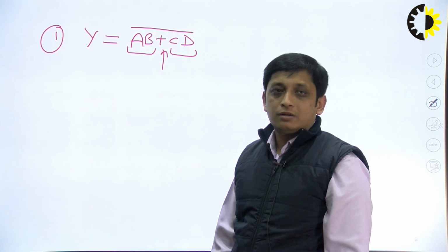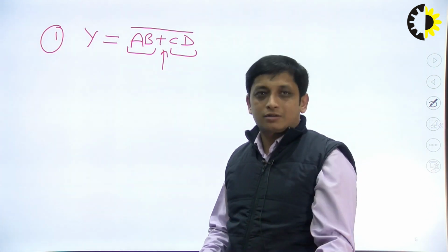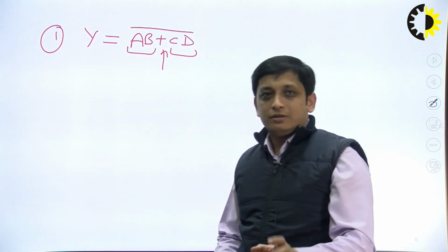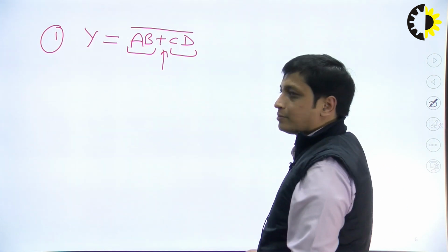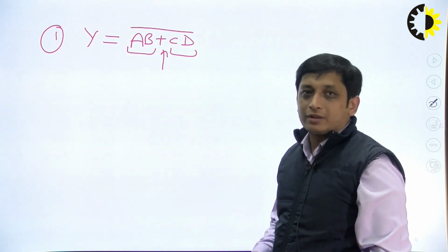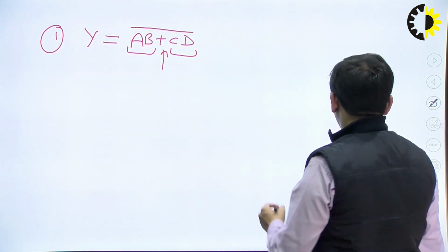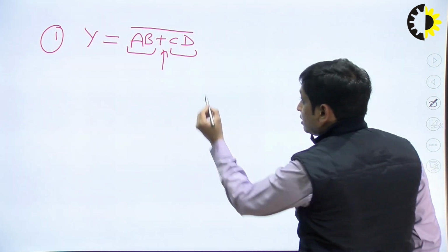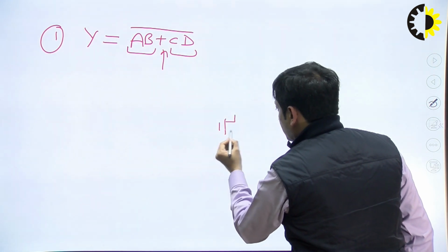Fine. So once we draw the pull down network, we can easily draw the pull up network, just interchanging the series and parallel. So firstly, I am going to draw the pull down network that will consist of NMOS transistors. See, A dot B, it means 2 NMOS transistors.